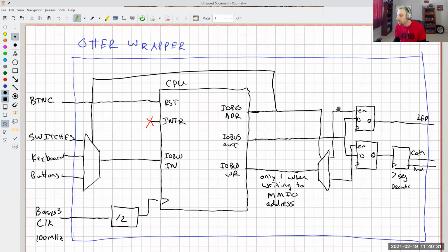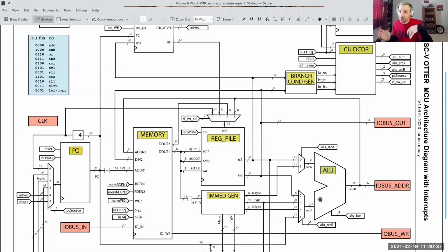So some of it goes back to maybe what we talked about, right? I said that your ALU should have all of your things happen in parallel as much as possible with one big mux, right? So when you think about longest path, you want to go through the least amount of stuff. And so you want as much in parallel as possible. So if you apply the same thing to this decoder, right?